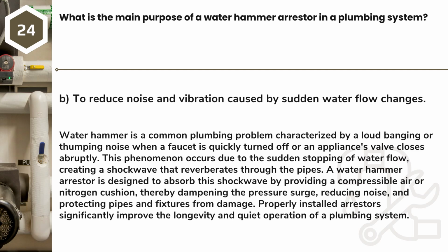Answer: B. To reduce noise and vibration caused by sudden water flow changes. Water hammer is a common plumbing problem characterized by a loud banging or thumping noise when a faucet is quickly turned off or an appliance's valve closes abruptly. This phenomenon occurs due to the sudden stopping of water flow, creating a shock wave that reverberates through the pipes.